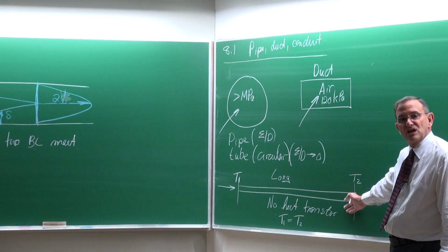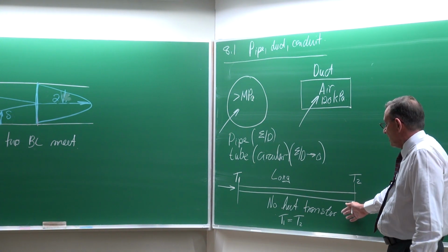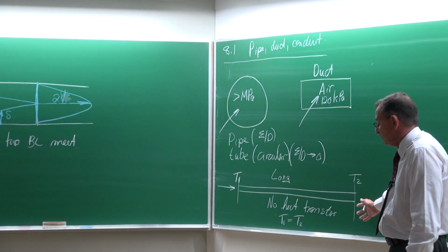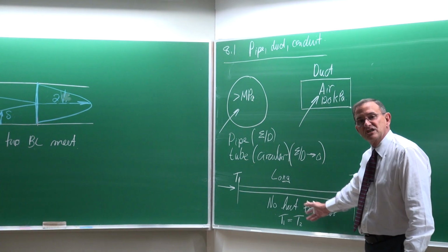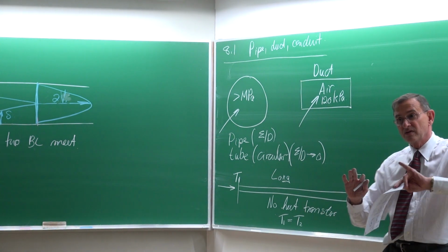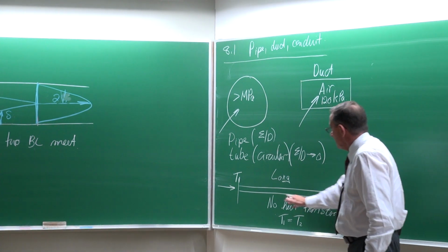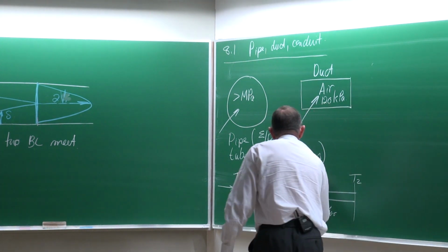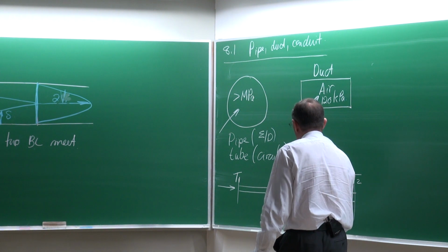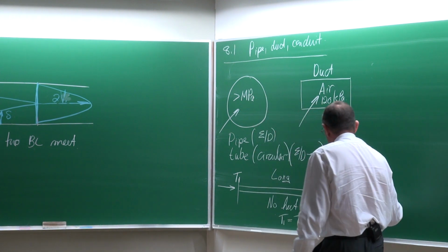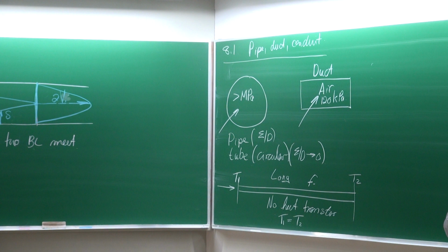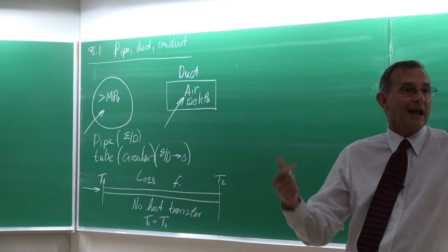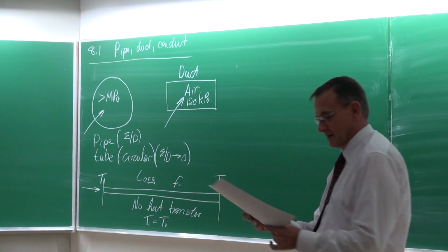In one of the previous lectures, I looked from first principles in thermodynamics at a few applications, and you'll see that if there's no heat transfer, but just flow through a very, very long tube, there's obviously friction involved, a pressure drop, so that pressure will be higher than that pressure, but there will not be a significant or a measurable increase in temperature for water or air. So you need to remember that.